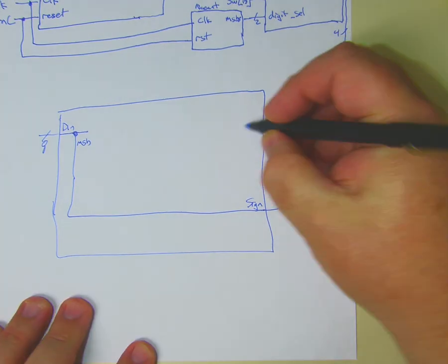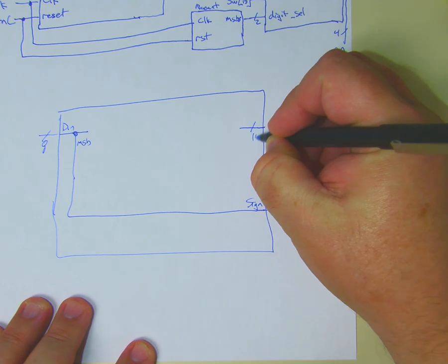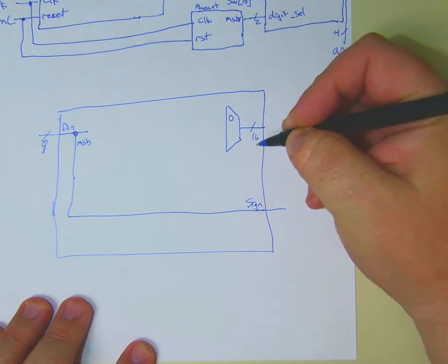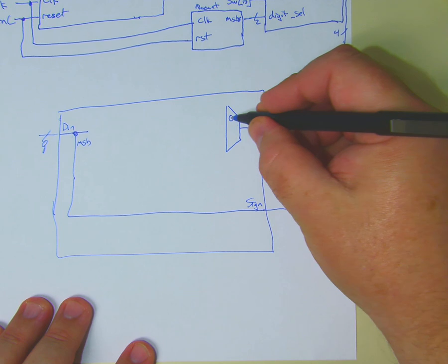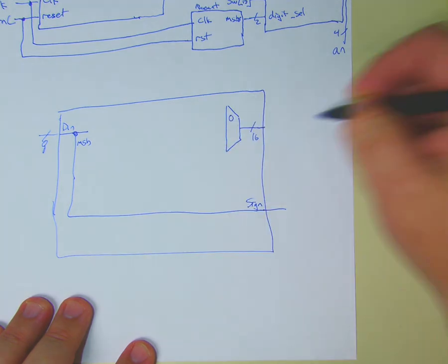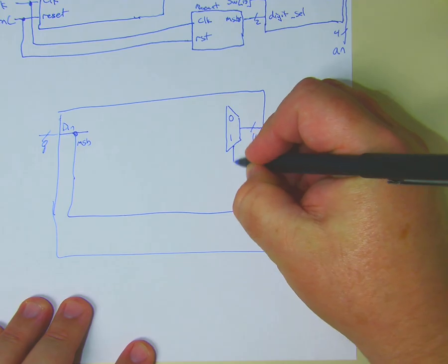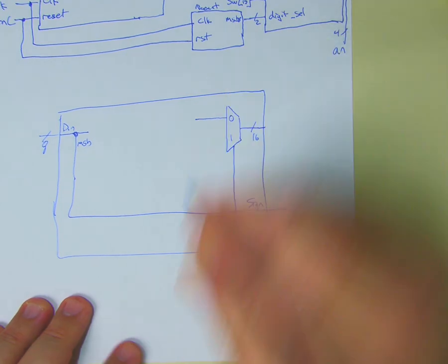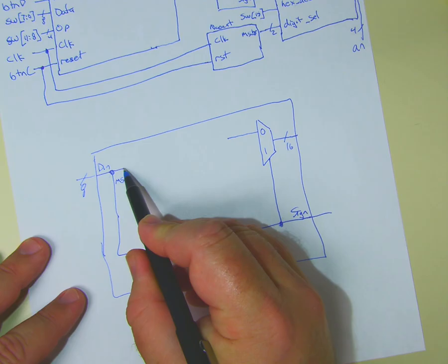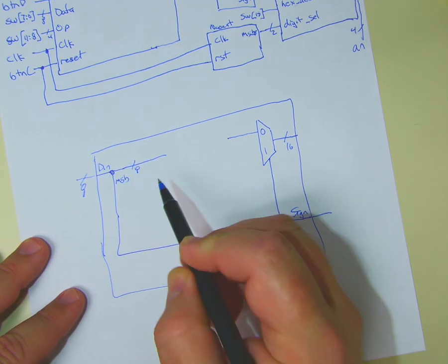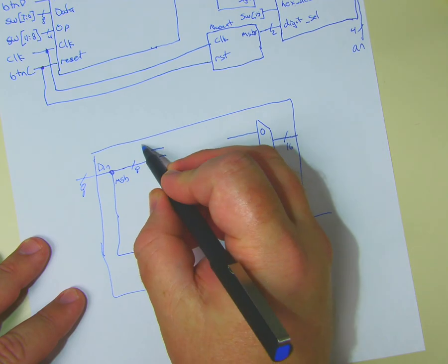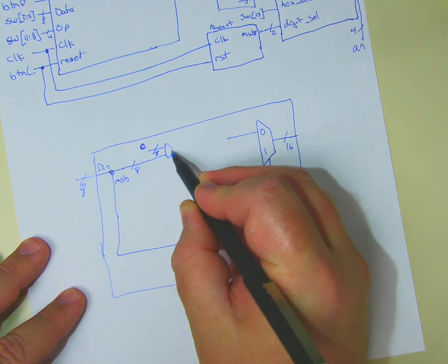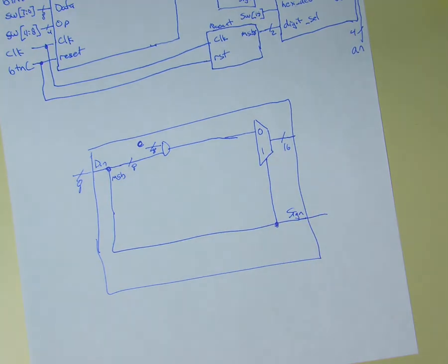All right, so my value coming out needs to be 16 bits. I'm going to have a mux. If it's a 0, then I'm just going to want to take whatever my number is, append some zeros, and pass it out. And the thing that decides is the most significant bit. So if this is the case, I'm going to take my full data in at 8 bits, and I'm going to append 8 bits of 0. I'm going to append them together, and pass those through. You agree?